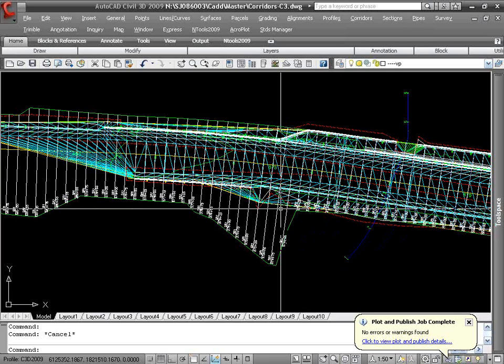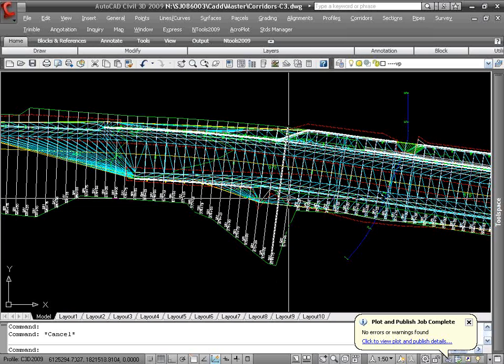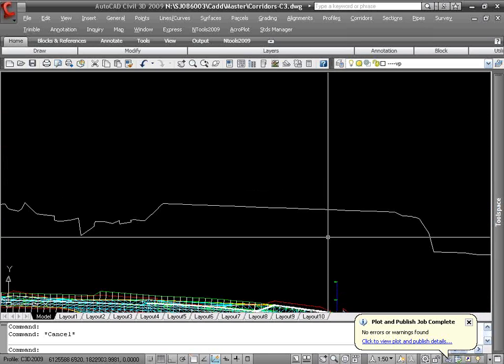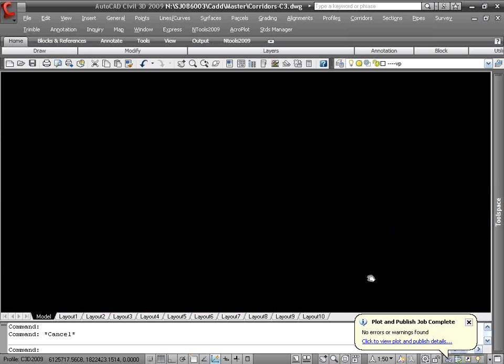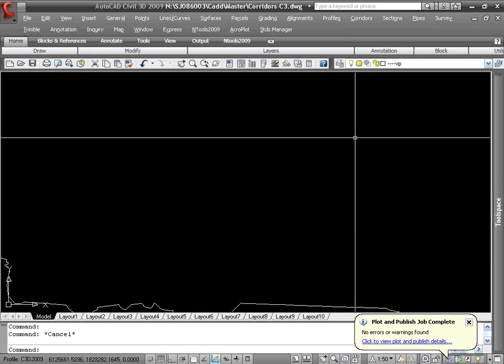Okay. Oh yeah, and for sample lines, there are right-of-way alignments. So the sample lines are just controlled by going to the right-of-way lines. Oh, that's why they go all the way. Is that why they're so wide right where you're at there? That they're following those green lines or the right of way? You got it. Okay. So, what he's done now is by doing that all in a single assembly with the assembly offsets, you'll see that he's got nice sections every 50 feet or whatever it is through this model, and both left and right widening, and then walls or whatever will show up in there.